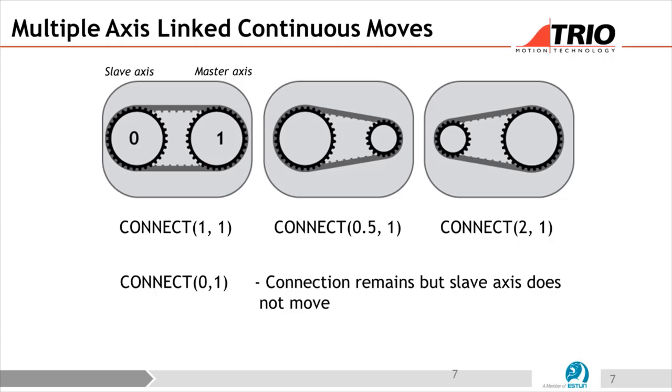Generally, in my experience, anything up to 5 you don't notice this effect at all. It's fine. When you get to 10 you might see a bit of nervousness in the axis. Above 10 and you're into a territory where it's not going to perform very well. However, the assumption there is that the master and slave axes have the same number of counts.